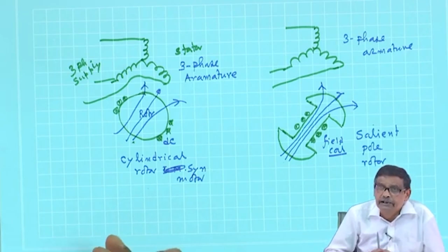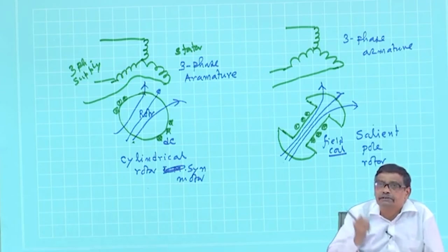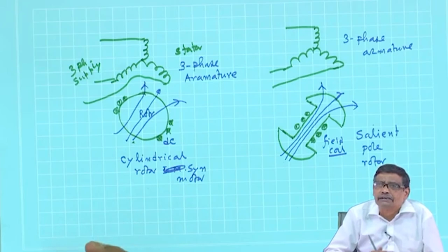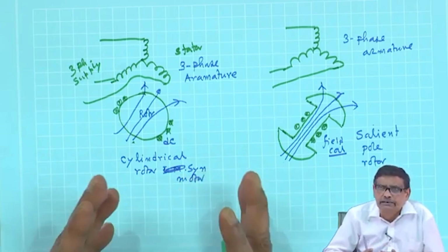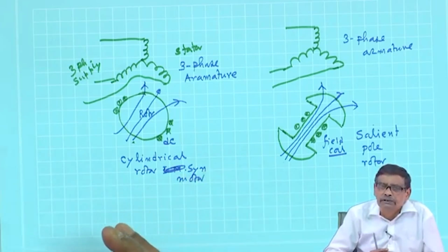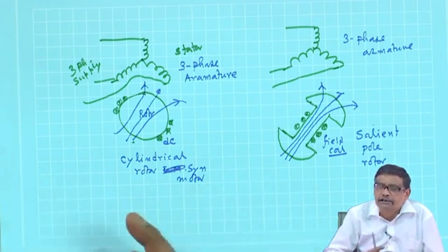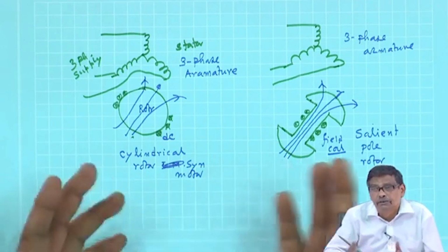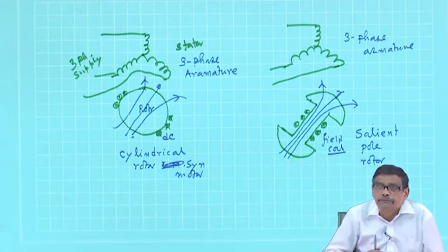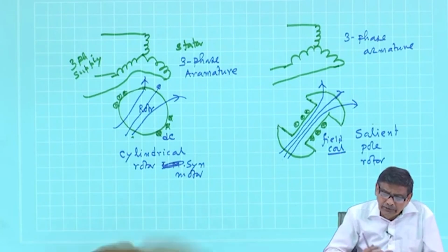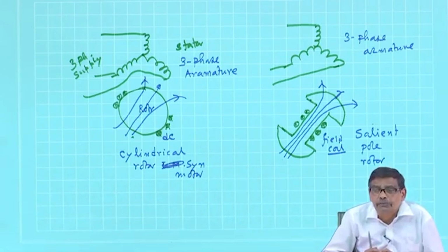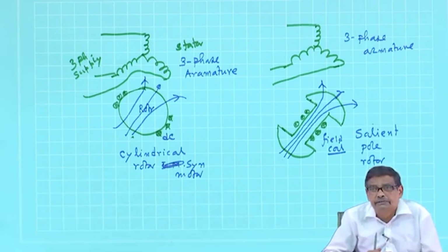So, a 3-phase induction motor draws the magnetizing current from the grid supply lines, which makes its power factor always lagging, no question of unity power factor or things like that. In lighter load conditions, the power factor will be much poorer. That was one of the greatest disadvantages. So, large size induction motor means large magnetizing current.